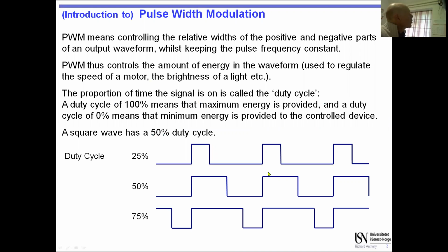So when we talk about pulse width modulation, we're talking about a voltage pulse, a pulse of signal on a pin coming out from the microcontroller, which we can connect to various things. But as I said a moment ago, mostly we're concerned with servo control, because the way a servo works is the width of the pulse governs the position. The servo basically turns to a certain point in different positions, and that's controlled directly by the pulse width.